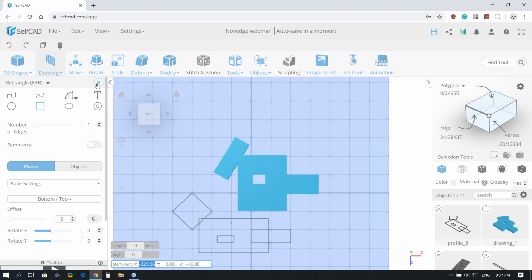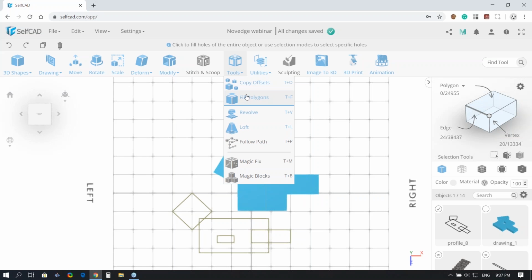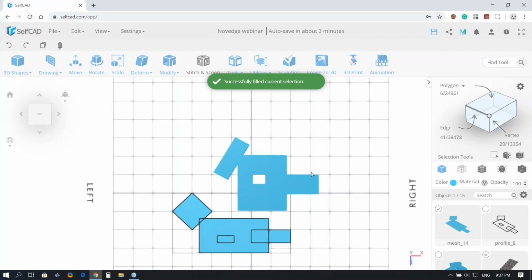Okay, so if I do something like this, I will need to start trimming away. And if I want to make the hole, actually, this will be even more difficult because I can't trim away now. If I delete this, this will basically already delete the hole. So I need to first fill polygons. And once I fill polygons, then I can go and select this. So now I have polygon mode, so I go to face mode, and then I can start selecting this case. In this particular case, this is just one quad, it's easy to delete.